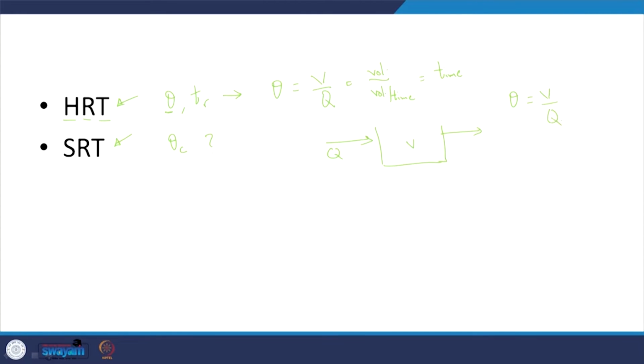But here in this particular process, activated sludge process, the system is not as simple as this. You know that from the sludge that has settled out, we are bringing in some microorganisms. So, as you can see here, the key aspect depends upon how many microbes are present or how much time the microbes are spending in this particular reactor. So, it depends on QR, again QR is a factor, let us look at that later.